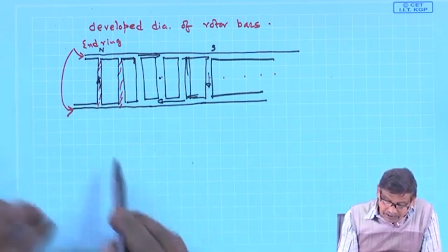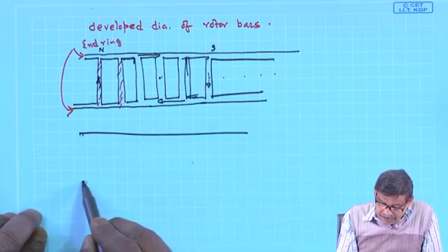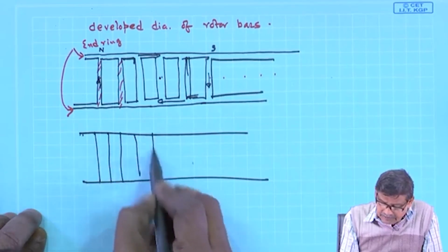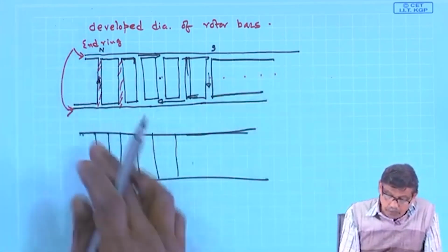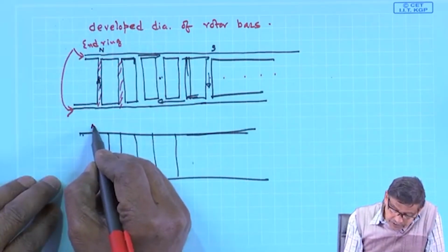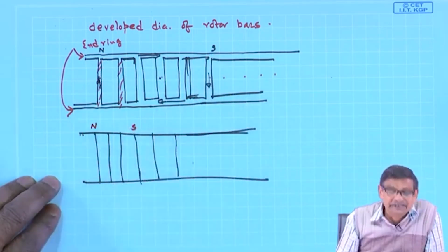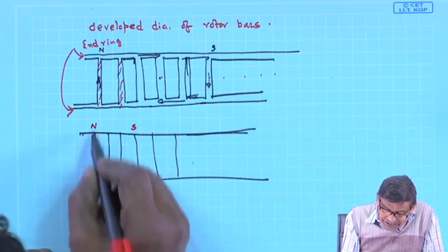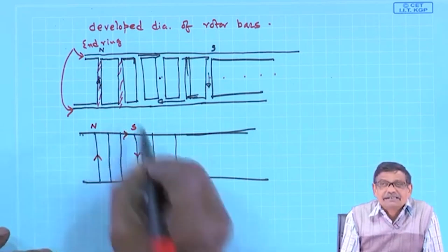Now, what I am trying to tell, I will now draw just like this. This is the end ring, and these are your bars, with the number of bars present like this. If somebody accommodates more poles created by the stator winding you have changed on the stator, suppose this fellow is under the north pole and the next peak of the south pole is here. Once again north, south. Here this conductor will feel, oh, my return conductor is here, I should circulate current like this.